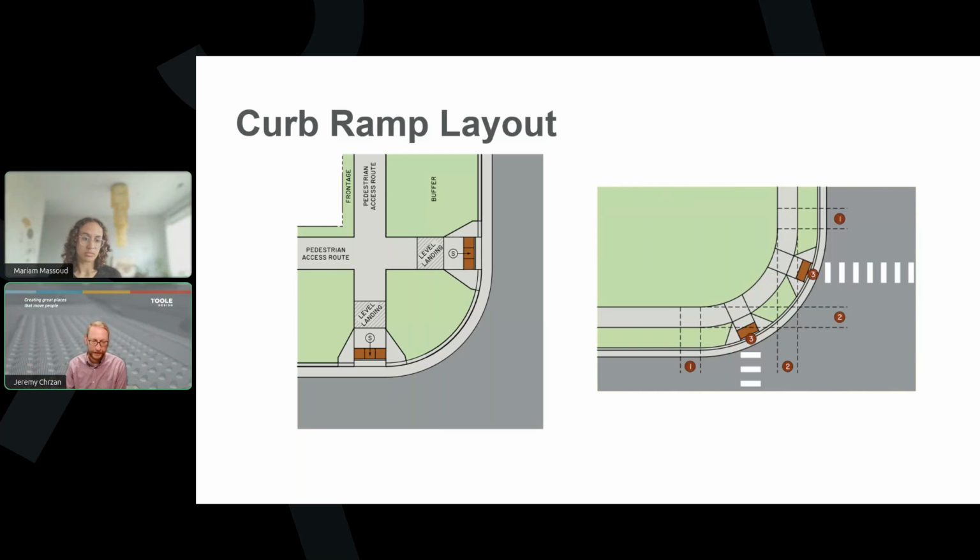And yeah, that's what I was saying with the previous answer, that the image as shown is probably incorrect, because at the top of the ramp, these are essentially parallel style ramps. Well, I guess they're perpendicular ramps that do not require a turning area at the top of the ramp. So a level landing would not be required there, but would be appropriate at the intersection of the two sidewalks themselves.